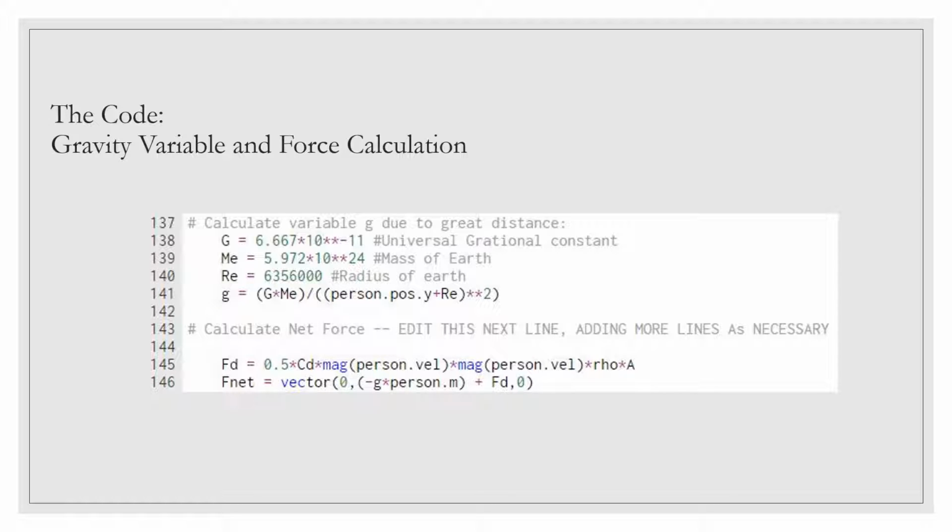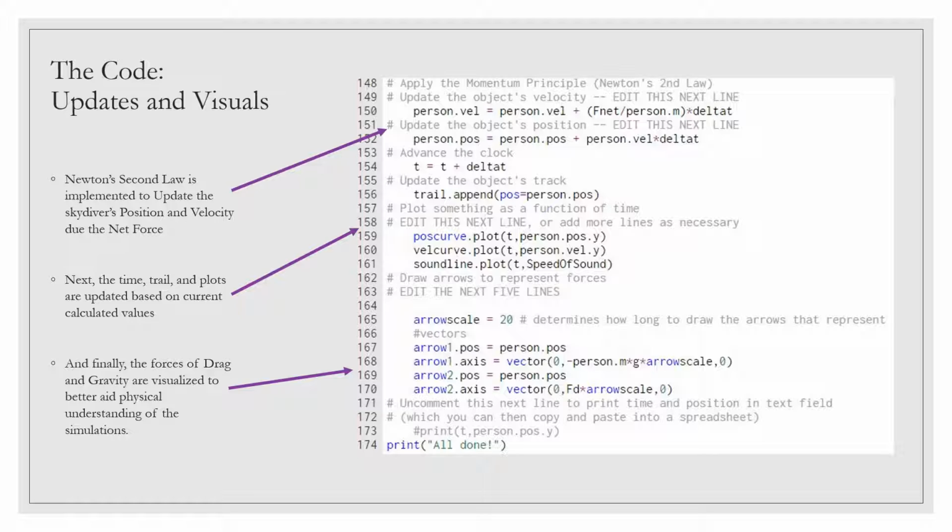Here, the acceleration due to gravity, g, is permitted to vary according to altitude. However, it was determined through multiple trials of code that no noticeable difference on predictions is made by the variance of g, and is therefore not considered as part of results comparison. Following this, the drag force equation is implemented and is combined with the force of gravity to produce the net force.